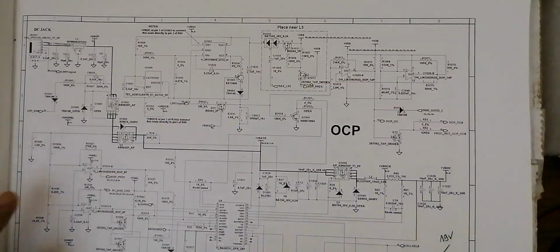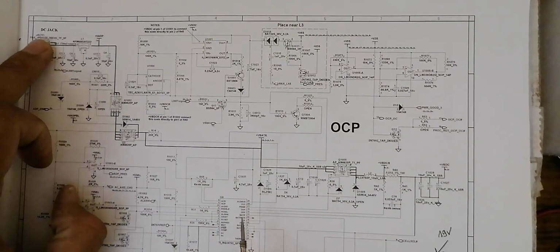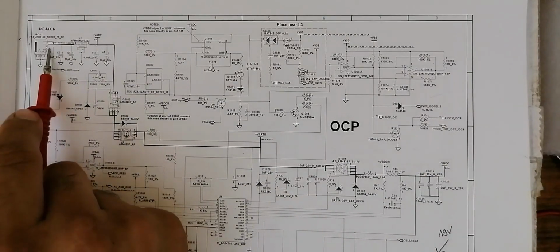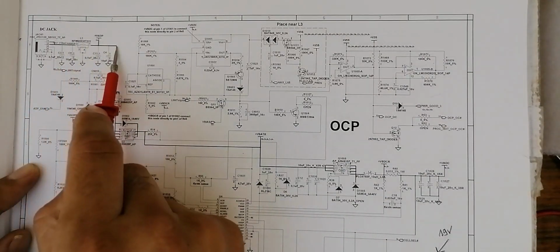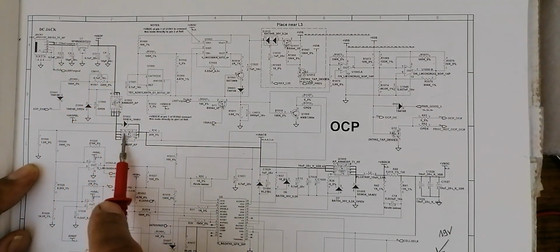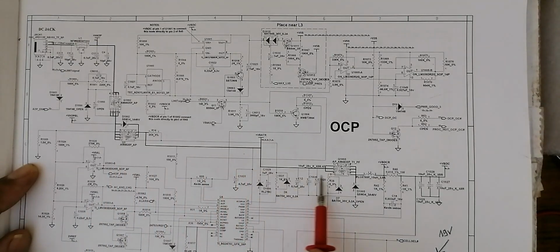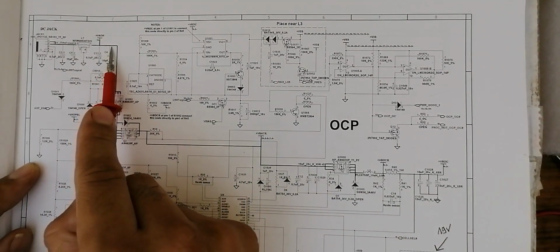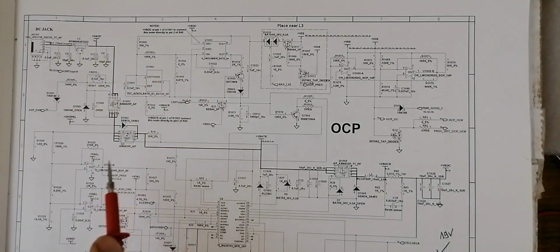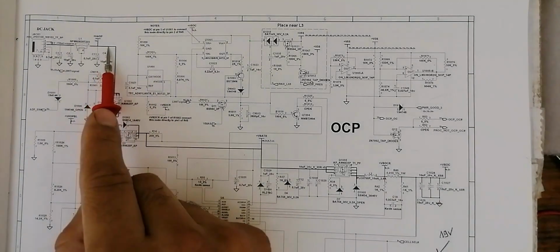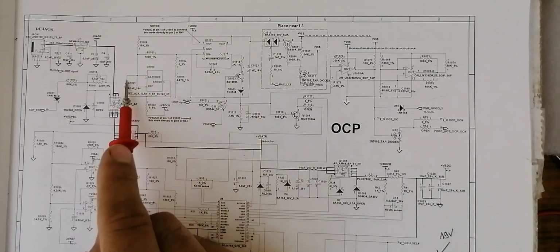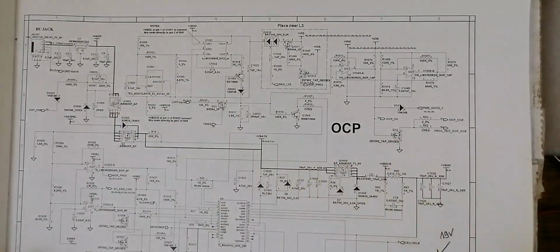So after the power jack, of course, so do you see here the DC jack? So after the power jack, we're gonna continue and checking the component that exists in the main power rails, as you can see. Do you see this line? This is basically a bolded line. This line means a high voltage. This is a high voltage, and this lines or path like this means a low voltage.